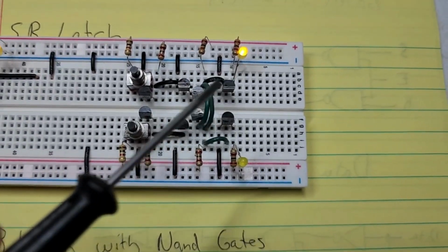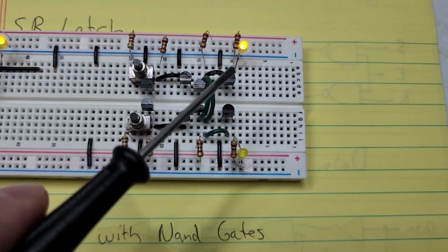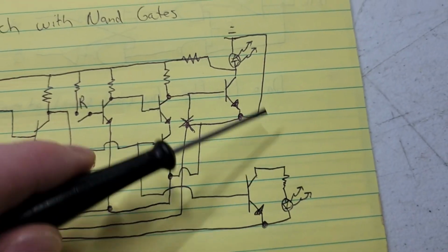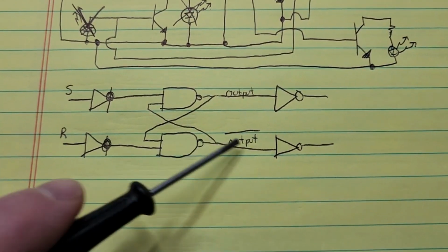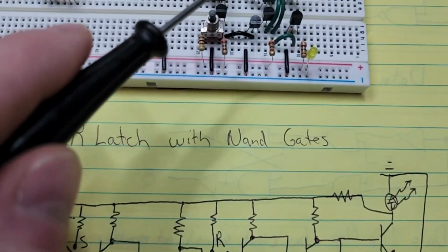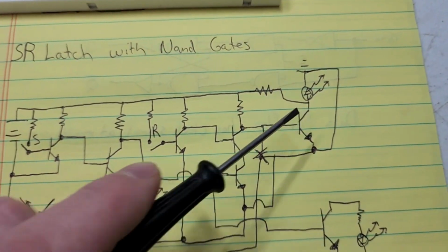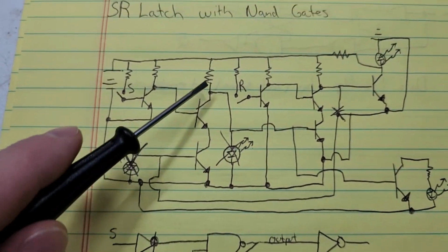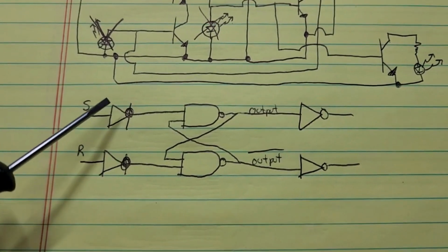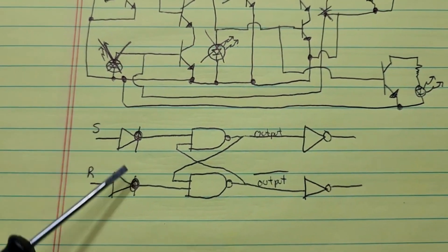You can see I got 4 transistors for each side. So these two are just the extra buffer that the LEDs are going to. They're these two here. And I think these are just buffers. Actually, these are inverters, right? They're set up like inverters. But the first two are just buffers. And so this is really what it is. It's 2 NAND gates, 2 inverters on the outputs, and 2 buffers.